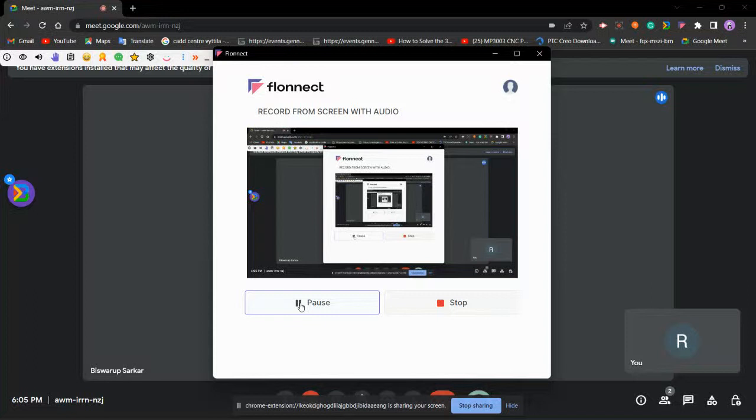Then we have thick feature, mirror extent. I've just turned off the thick feature. Then if I go for this more option, I will get this thing again. And the second limit can be controlled from here. The second direction limit can be controlled from here, or in the same way, we can drag, move our cursor towards this, and give a preview.